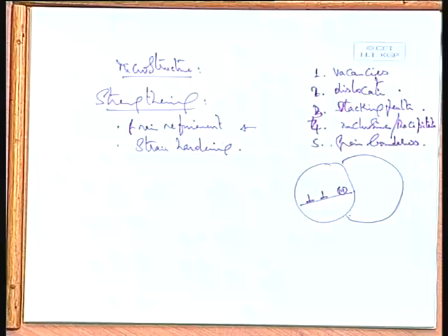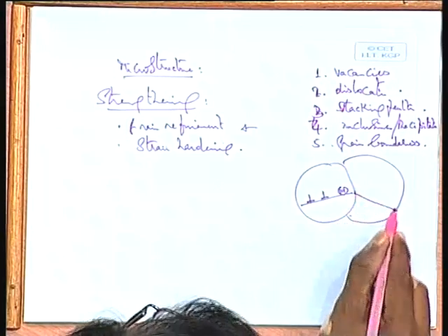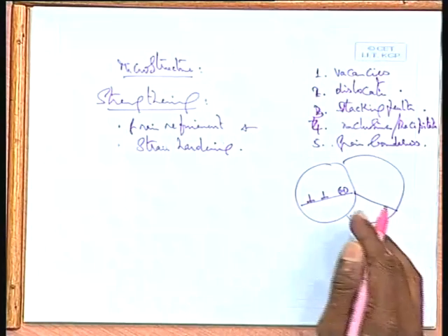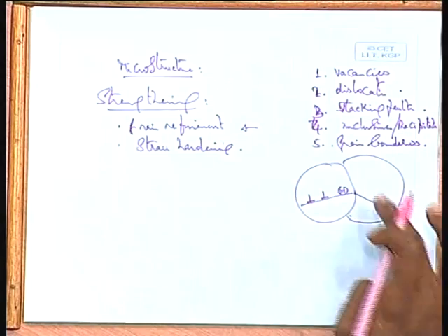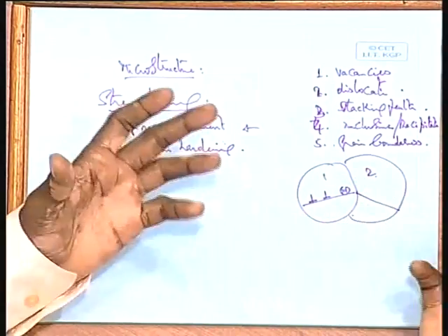If the plane is continuous into the other grain, then in principle you do not call it a second grain at all. What is the definition of a grain boundary? It is a boundary where there is an orientation difference. That means this plane, let us say a 111 plane in an FCC crystal, is oriented in a different direction in the other grain. If it was not, grain 1 and grain 2 would have been the same grain. So a grain boundary basically represents an orientation difference.